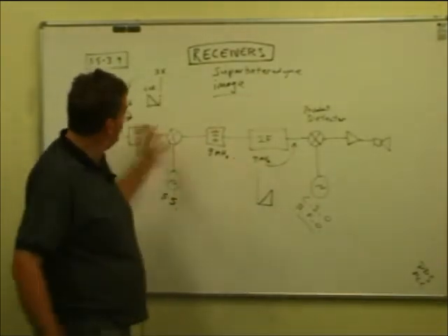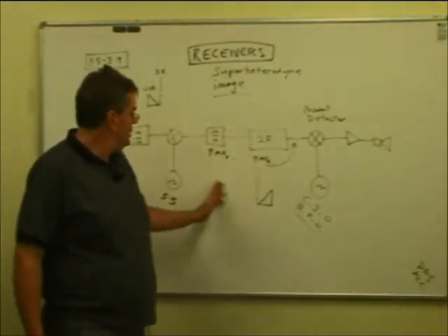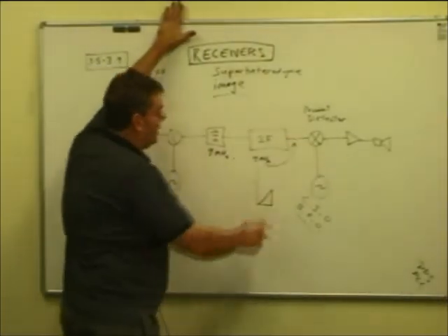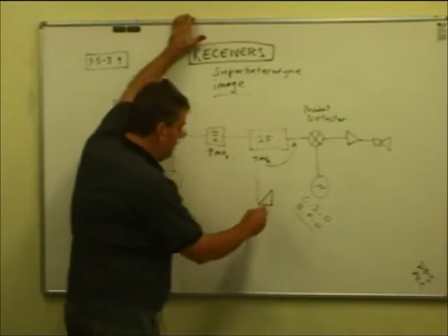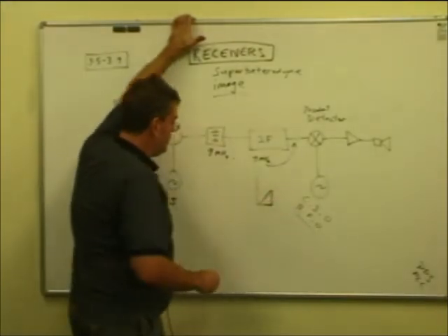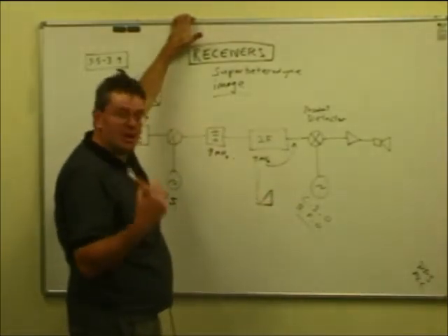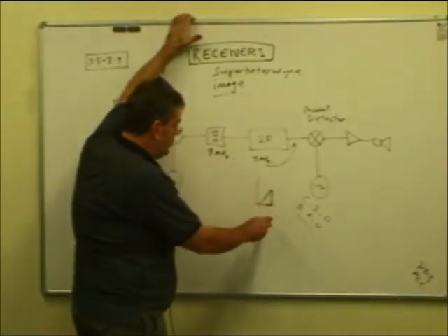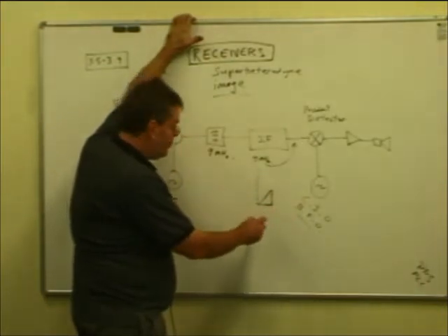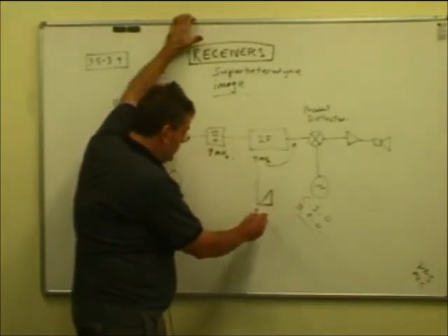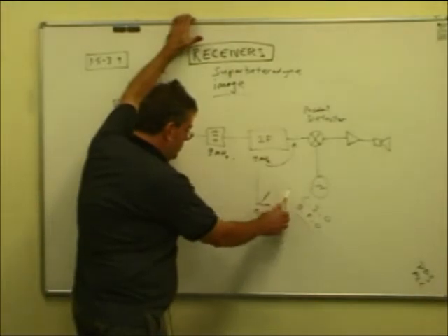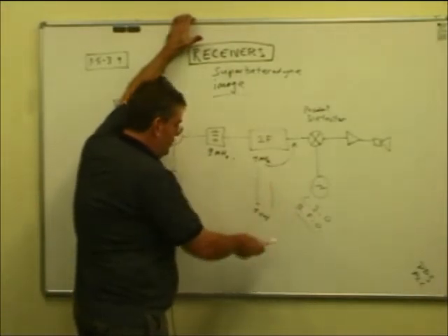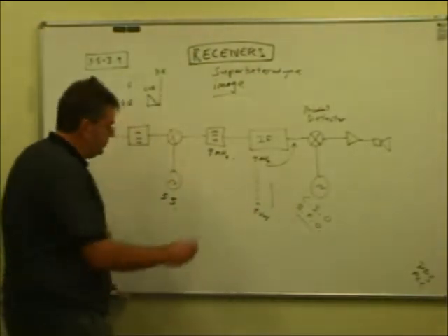Things get put upside down because of the way the frequencies are mixed, if you do the maths, but we don't need to go into that. Just suffice to say that coming out of the IF amplifier, there's no carrier, and we've got our intelligence just spread over a range from 9 to just above 9. So if it's a 1 kilohertz tone we're whistling, coming out of there will be 9.001 megahertz. But when there's speech, there's a whole bunch of signals there.